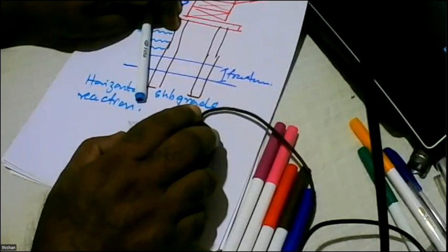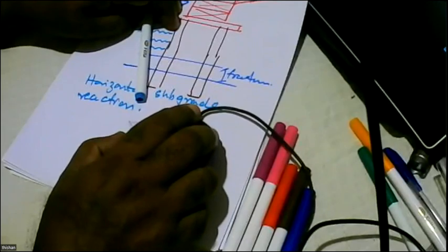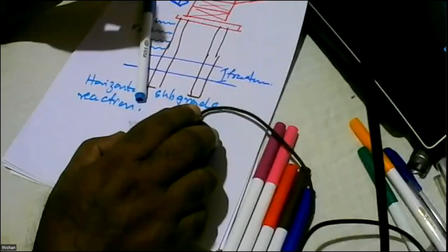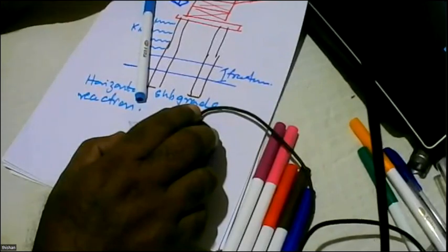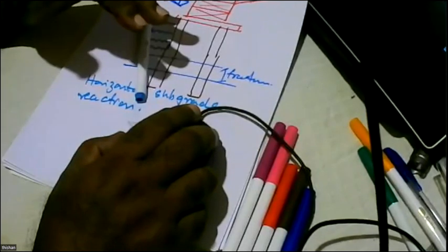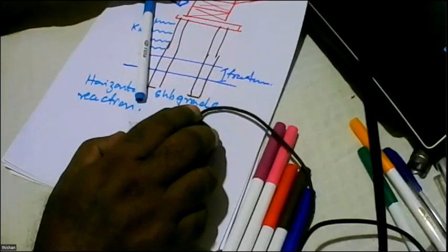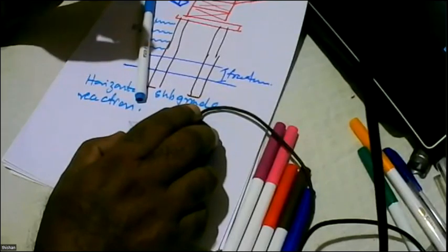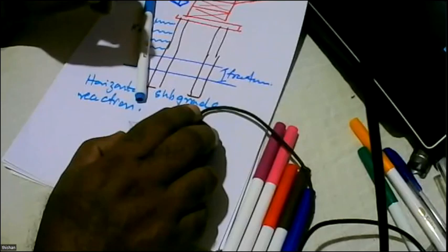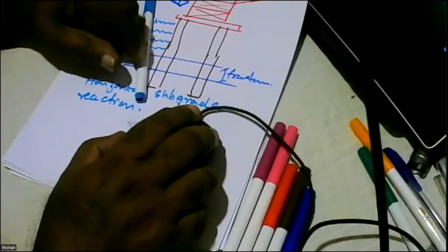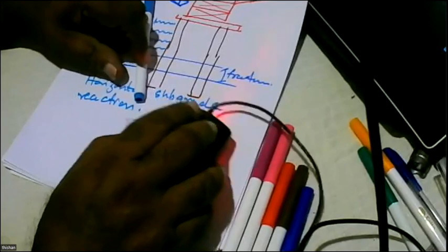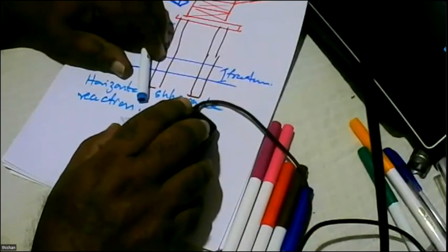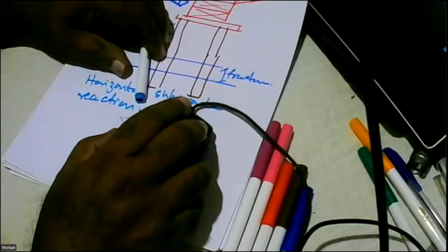That means the water table is high in this area because this is a river. We are considering a bridge. The river is full of water. The water table is high. Though we have good soils, a sand and clay mix, it is going to behave more like a clay soil. So we have to see what type of soil is available.